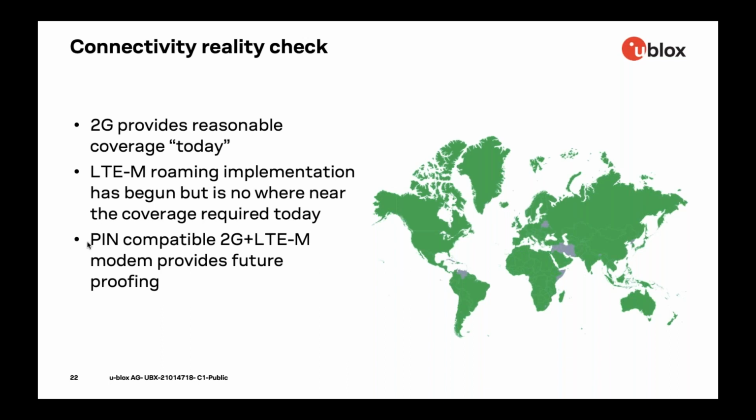The original product was 2G only and is still being sold in volume. But there's the LTE-M variant flowing behind, and that's really to give the connectivity. I don't think the design necessarily will worry too much around PSM or redirects. It's very much about continuing to adopt and use the MQTT-SN protocol to provide the driving savings, or the main savings, from a power perspective.